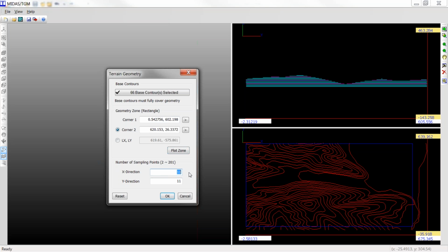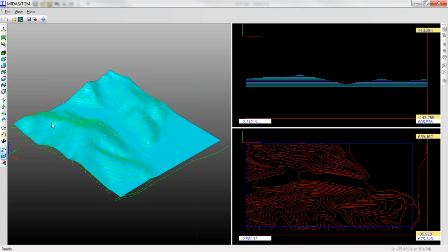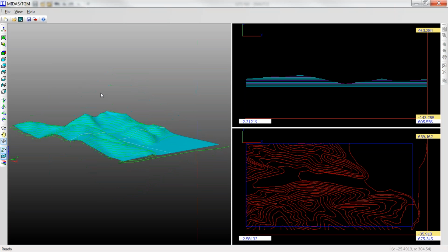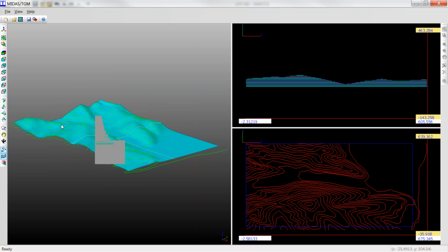And here, the more sampling points you give it, the more accurate it's going to be. So we can just say something like the range is 2 to 200. 40 is sufficient for this case. And we see here if I rotate it, it's actually pretty accurate in terms of what the deformations of the geography, topography are. So I would just go here now to export surface.